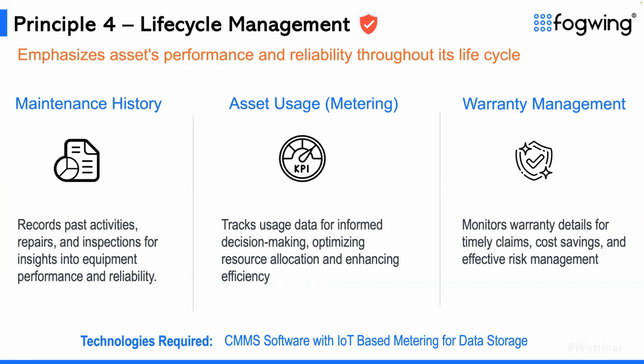So we need history data about the machine, past maintenance activities, what kind of repairs happened in the past, how frequently these repairs are happening. So we need a maintenance history, and we should capture that and put it in a more accessible environment, so that we can easily analyze this history of the activities to understand how long the machine is being used.